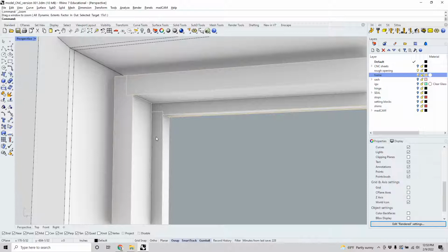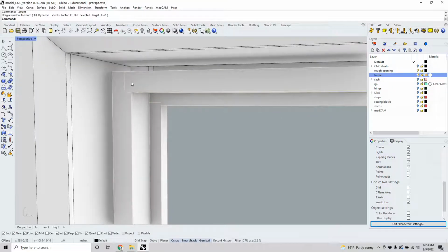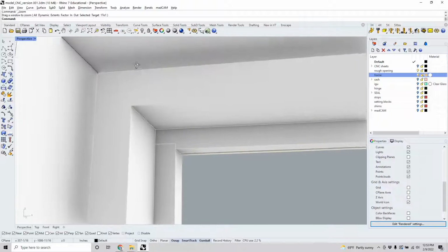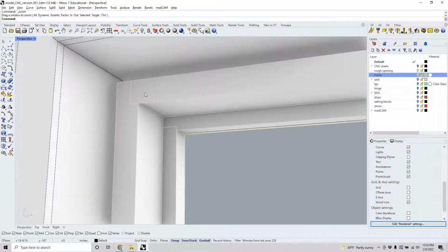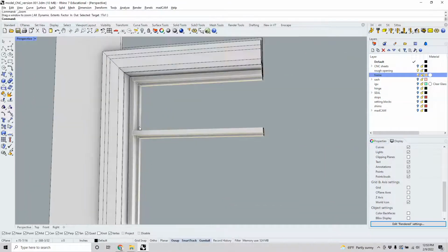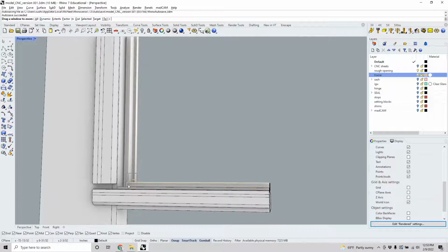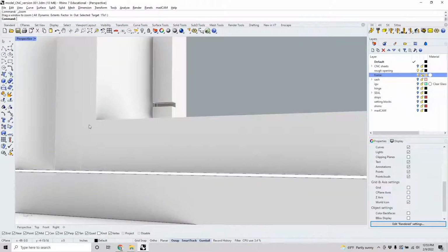And also, traditionally, the wood frames were made with mortise and tenon joinery, which obviously I would prefer, but given the digital fabrication techniques, I would use a rebate here, or a rabbet, whatever you want to say, a dado here, and similarly at the bottom, another rebate. Right there. It's just easier for me to fabricate.